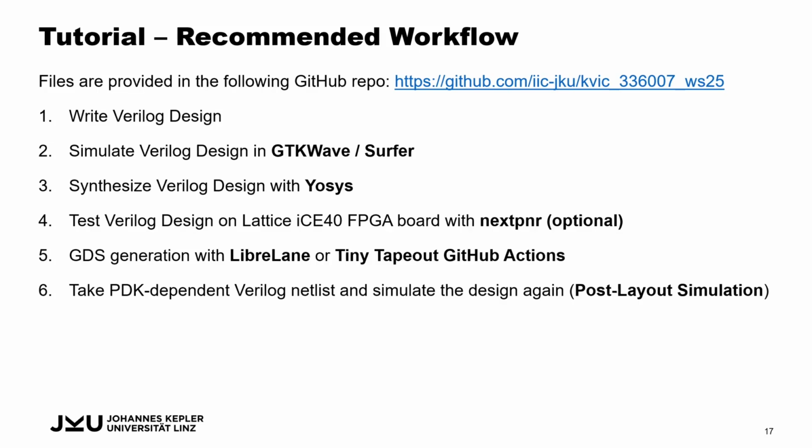So you can upload your Verilog code to these GitHub repos and then run your GitHub Actions. Then the GDS is also generated with LibreLane in the background, and you will also have a nice 3D viewer or 2.5D viewer, where you can verify and check out your layout.